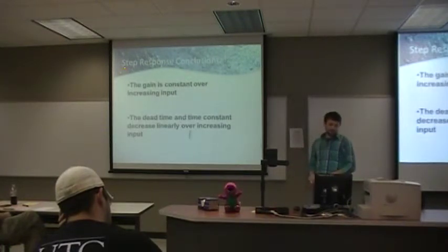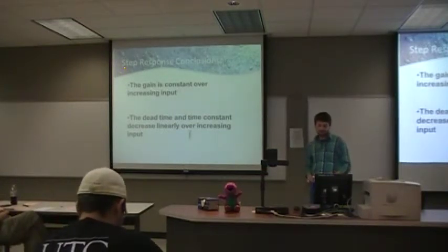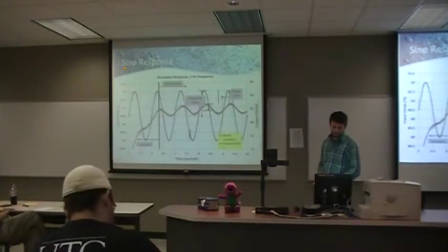In conclusion, for the step response, the gain is constant over increasing input, and the dead time and time constant decrease linearly over increasing input.